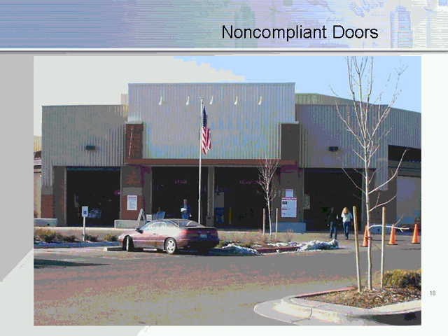Another non-compliant door, and in this case, we need to take a look at this and determine which of these doors would be fair game and which would maybe be exempted from material handling. The entrance doors into this particular store, if you're not pushing materials in there, could be considered fair game from a vestibule standpoint. The exit doors on this, depending on what the particular store sold, you might be able to make a case that you could exempt vestibules off the exit doors. But again, this is another case-by-case standpoint. You need to really take a look at the need of the building to determine, is it exempt, or do you actually need to comply with the code for this particular door?